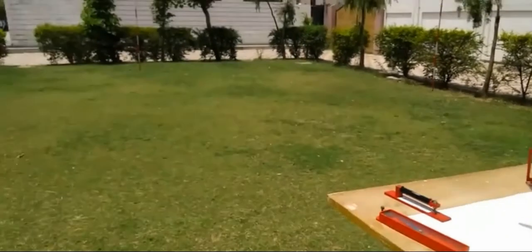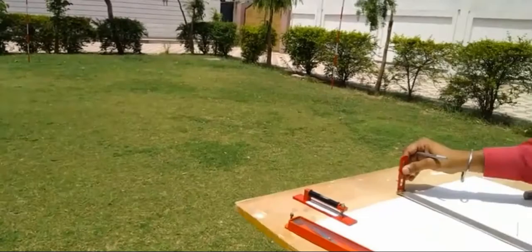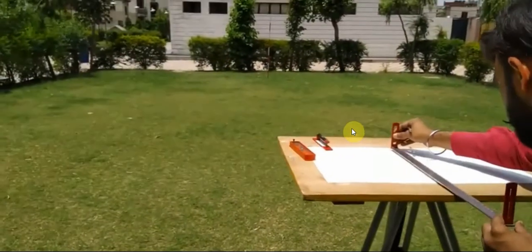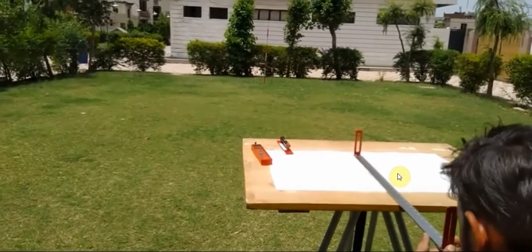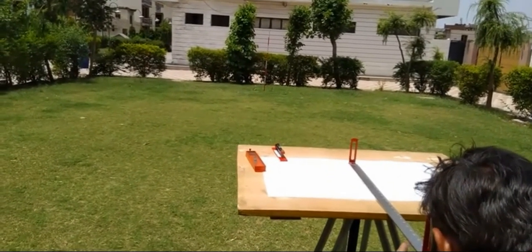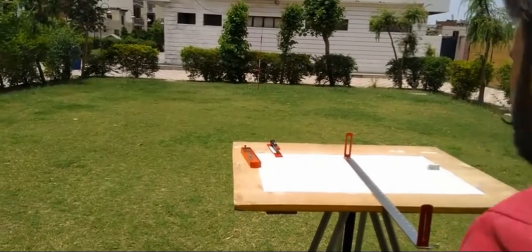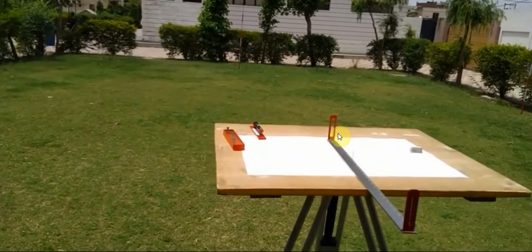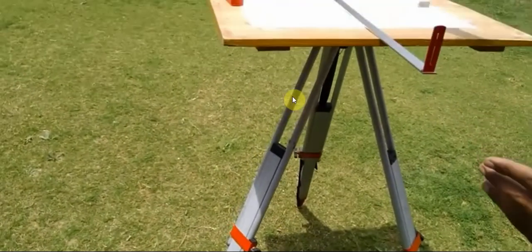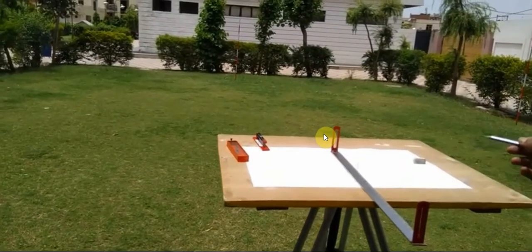So next what I'll do is I'll sight the next point, that is point B. I'll keep the alidade against the point O, that is station O. I'll sight through the narrow slit and I will sight point B. I will make this crosshair or this thin hair bisect the ranging rod. Then again I will draw a ray against the alidade.